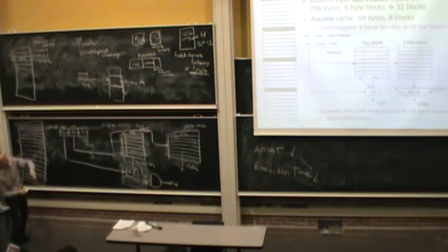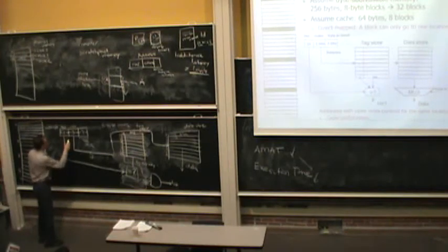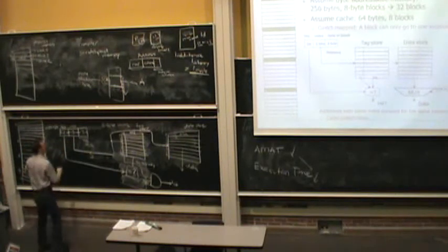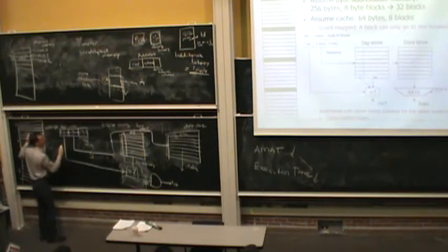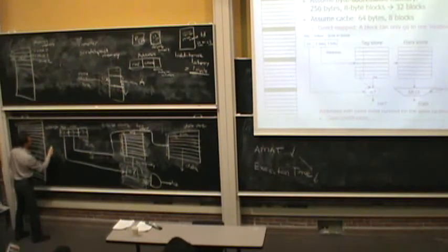Well, I guess there's more, right? Because these all map to the same location because, no, that's all. Yeah, because it's a 32-block memory. These all map to the same location because they share the index bits, right? They have the same index bits. So if you look at address 0, what you have is index bits 000, your tag is 0. And I'm going to omit the remaining.